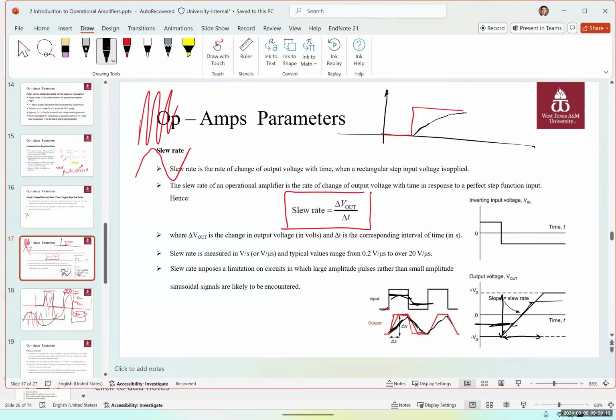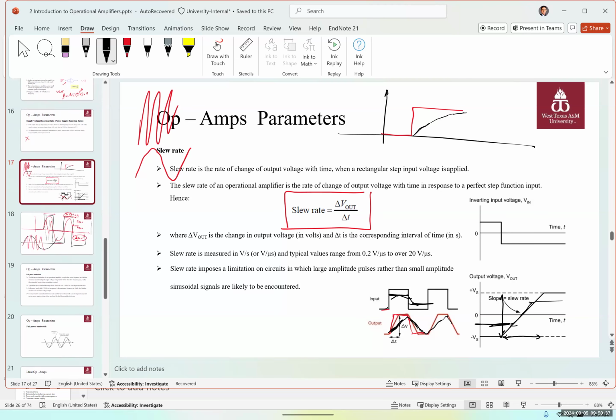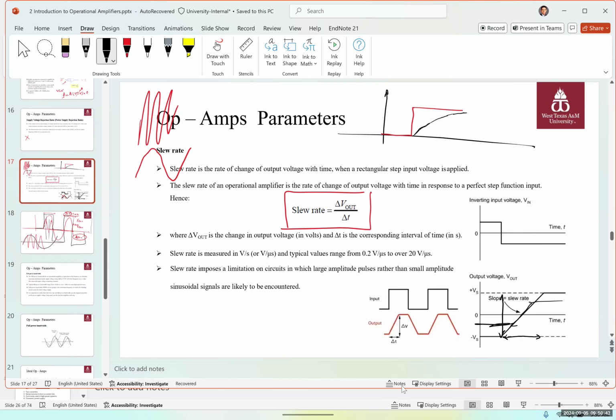Yes. So if I could jump higher in 1 microsecond, it means I'm a faster, stronger person, or a stronger, faster op amp in this case, compared to the op amp that could just jump from the floor to the chair. Okay. So a 20 volt per microsecond system would look something like this, which is much closer to the ideal. So this is 20 volts, for example, and this could be like a 0.2 volt.